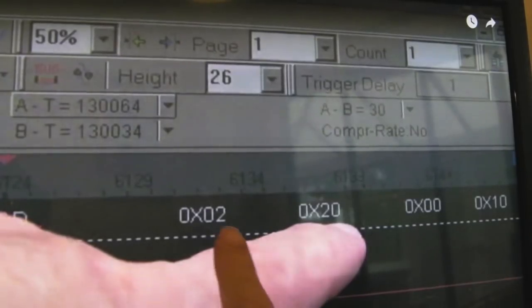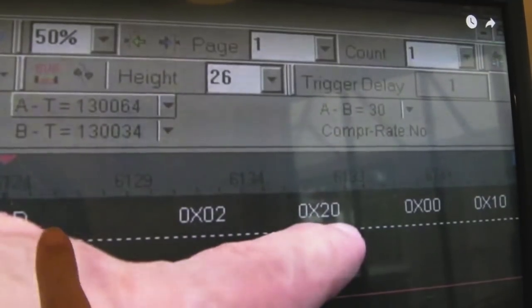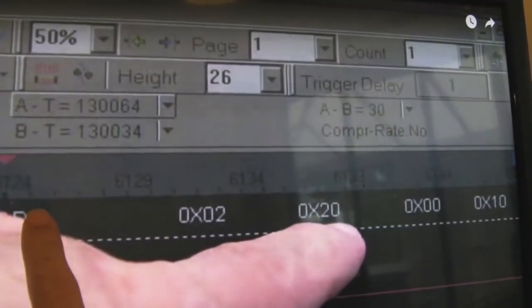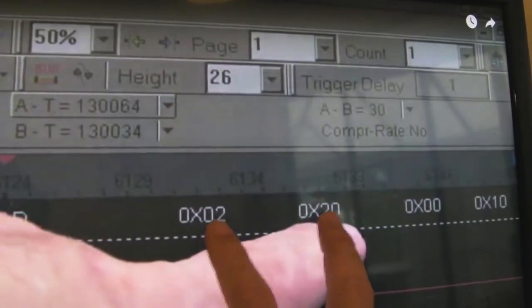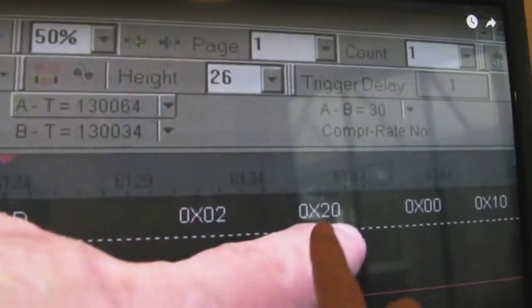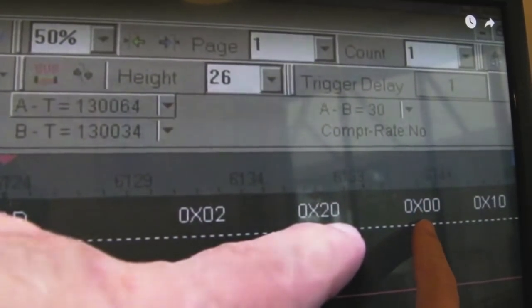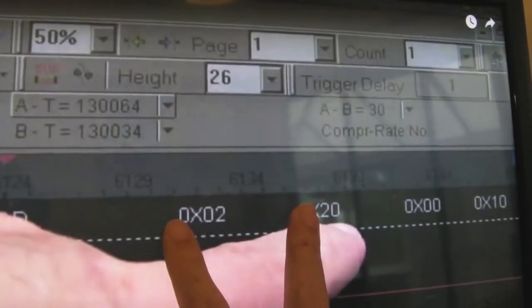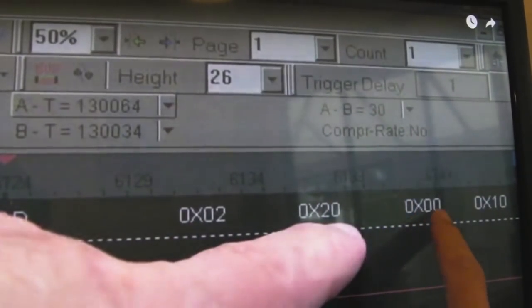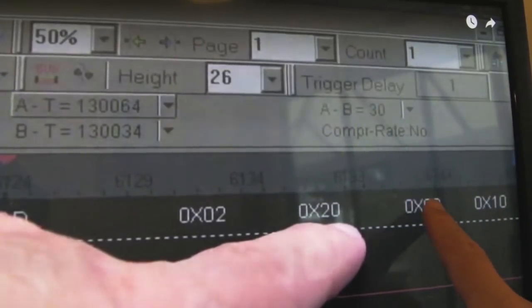Something else to clarify, on the point where we did the capture on the logic analyzer there, you could see the read here. You can't quite see the instruction, but that was the instruction we were looking at, and it was reading from these two bytes here, address 2002. They go in reverse order. And this 00 was the CPU, after it had read these instructions and read the address in, the next thing it was doing: reading 00 from the PPU. So that was a read, not a write.